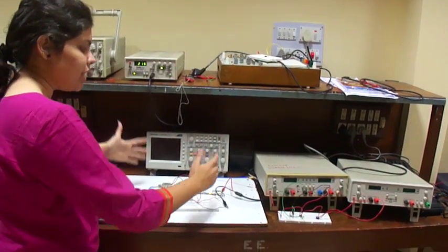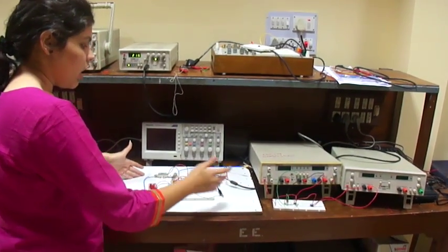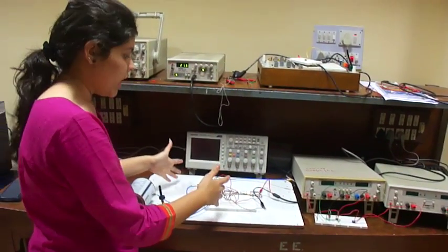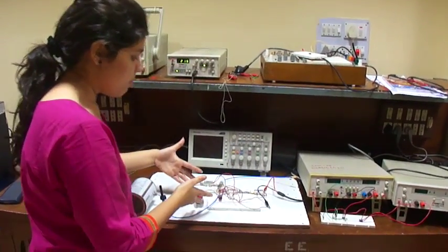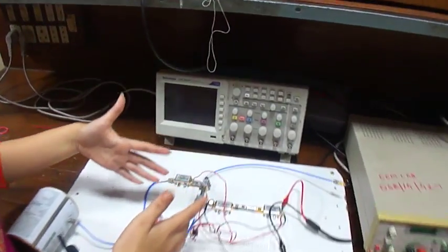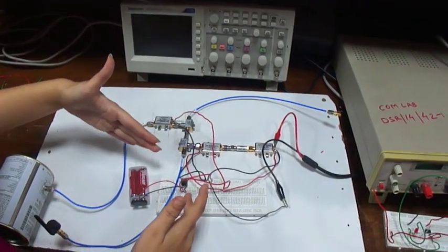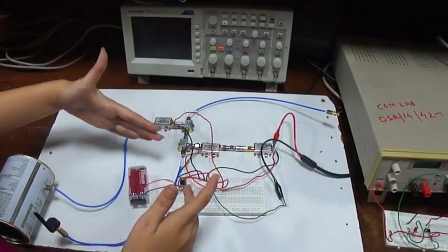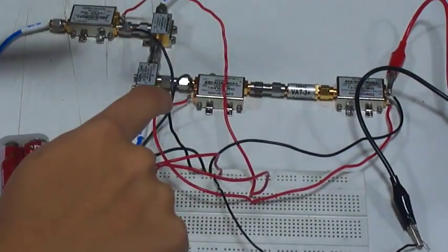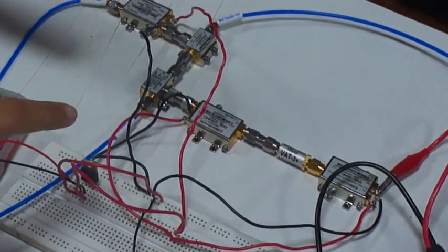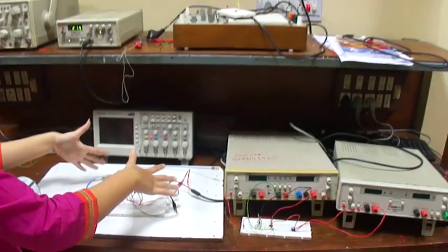Now here, all these ICs require a supply of 5 volts. Now we need this device to be handy as it is to be used in mining areas. So we have used a battery pack which provides 6 volts. So to bring down the voltage to 5 volts, we have used Texas Instruments IC 7805, which can be seen here. Now this steps down the voltage to 5 volts, which is given as the input to all the ICs.